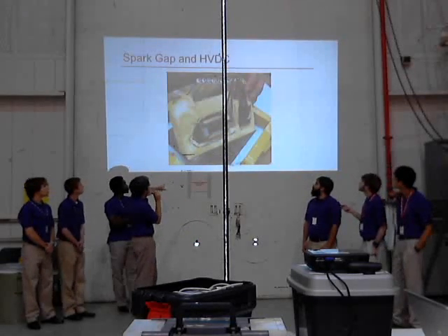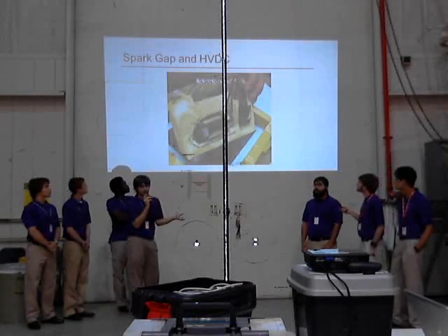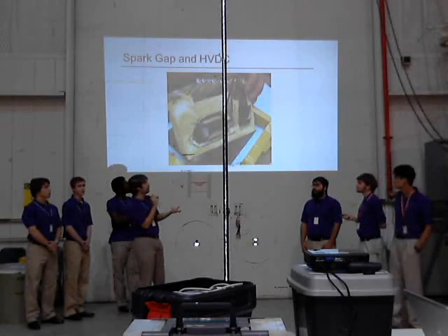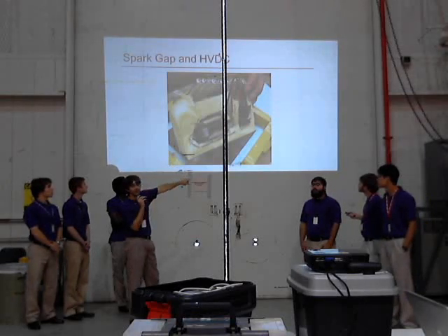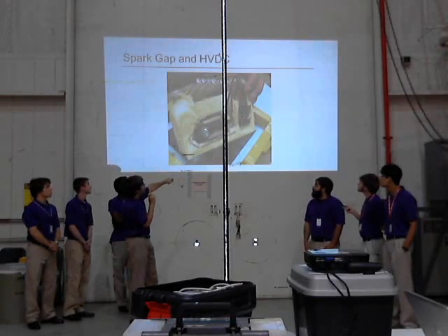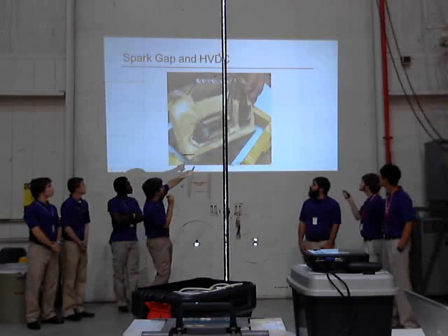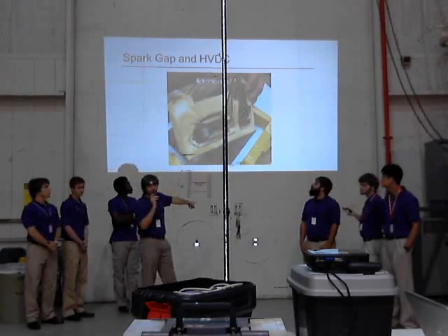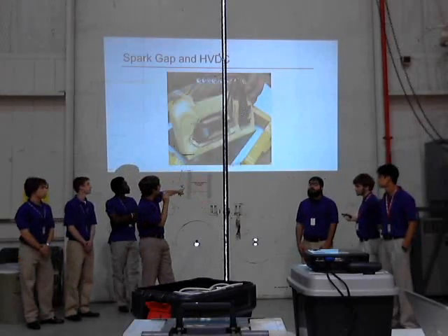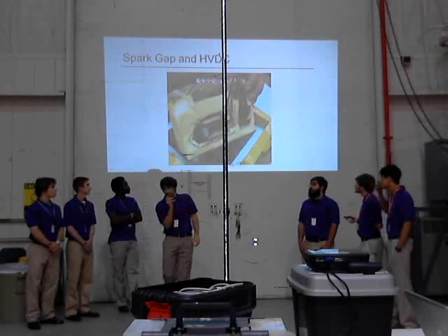This is what that foam block looks like. We took a mold, filled it with Great Stuff insulating foam, and then carved out the necessary parts for the high voltage converter, which is on the right, and the spark gap, which is on the left. You might notice that the high voltage converter has a huge block of black stuff above it. That's high voltage potting compound, which John will go into right now.